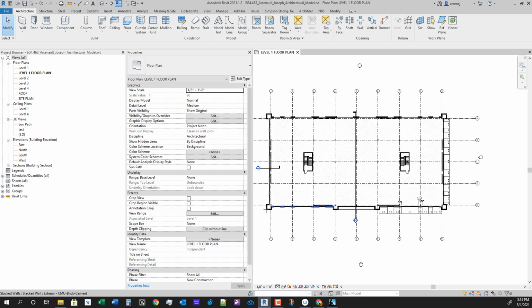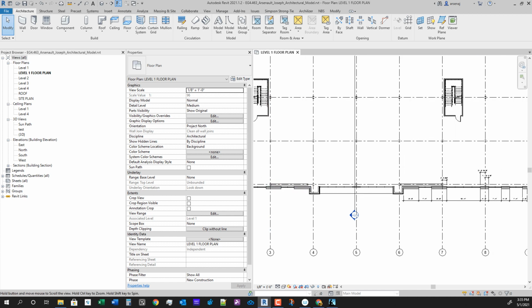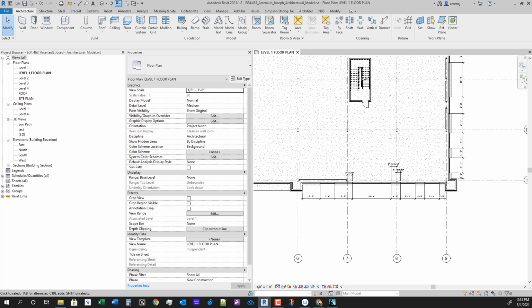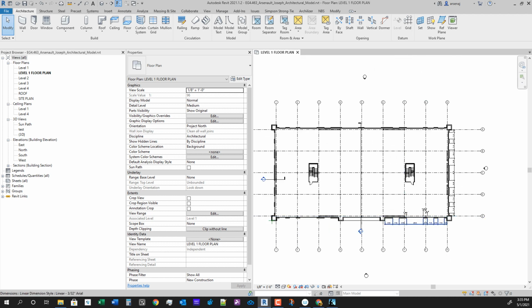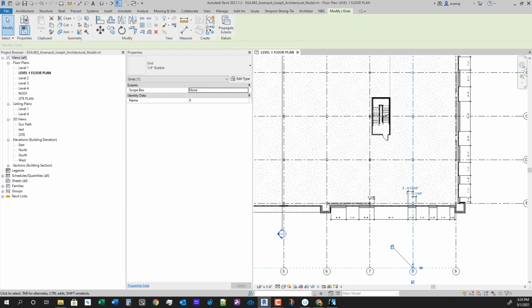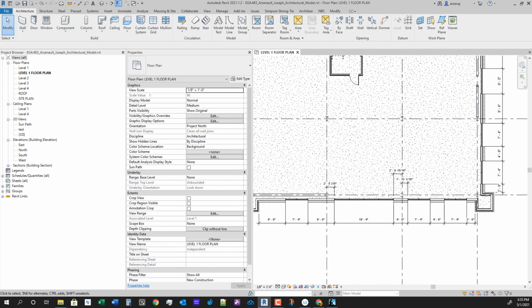Right now we have our columns spaced evenly throughout the building. I'm going to adjust them to be more symmetrical within our windows. So once you get that open, we'll go to the bottom right corner at the level 1 floor plan, come down here to grid 8. We're going to center this on this 4'8" wall chunk here.